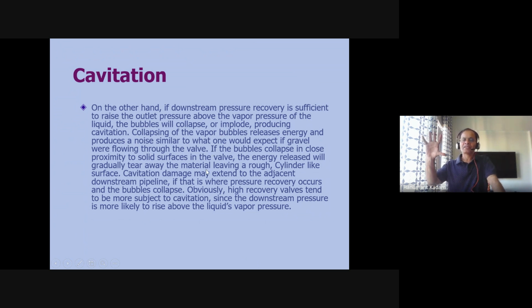Gur, gur, gur, that sound is common. If the bubbles collapse in close proximity to a solid surface in the valve, the energy release will gradually tear away the material. It has high energy when the bubbles explode, and that is cavitation. Because of that, the internal part of the valve body gets damaged.